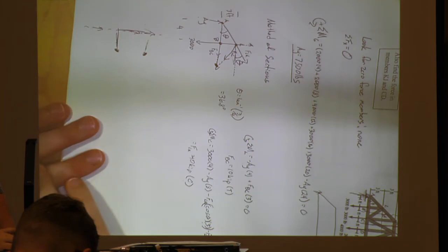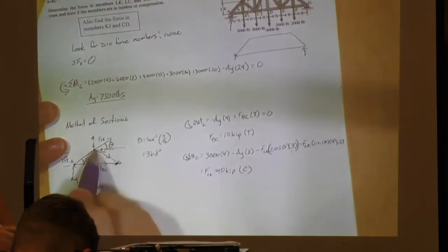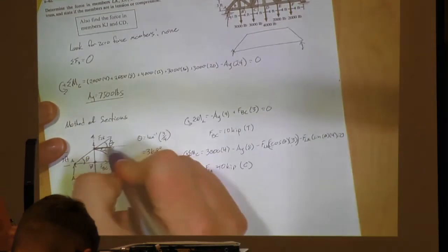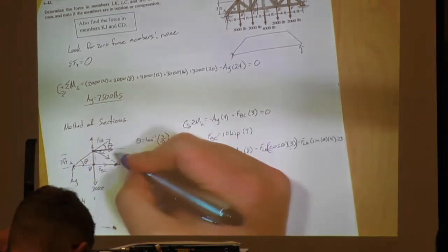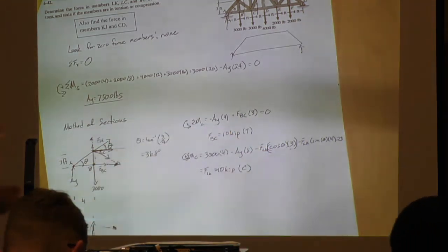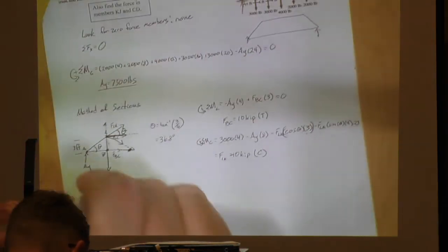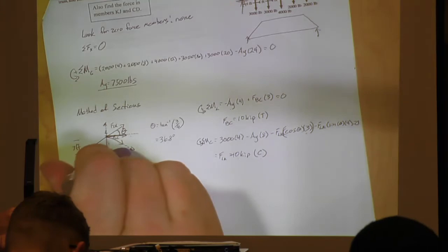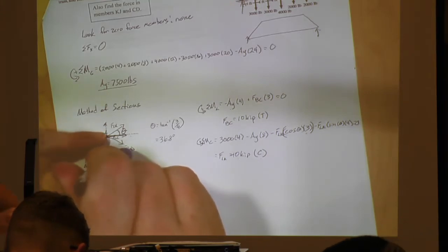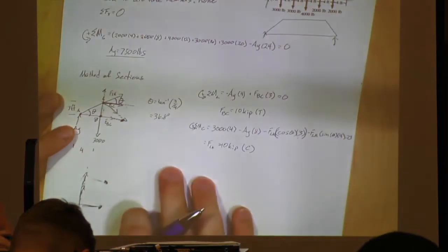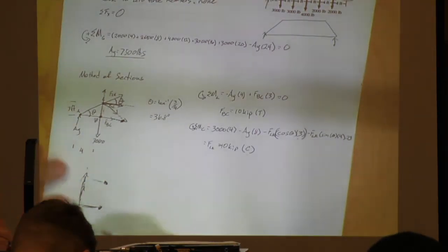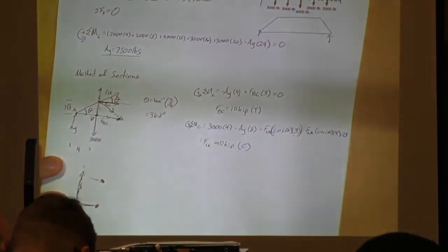Does that make sense? So up here, our x is right here, and our perpendicular distance is 3, because from here to here is 3, so it'll still rotate. If you have any questions about whether something will rotate, take your pen, and say I have an x component, see if it rotates. I have a y component, see if it rotates. Okay? It gives a little bit of a visual. If you have any questions about it, just put your finger on it and try to push it. All right? Question?